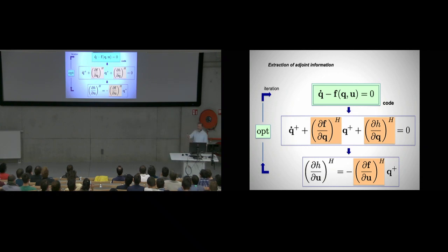Okay. And one possibility, there are many possibilities, but one possibility is you sit down and you derive it. You take your equations and you go through exactly that integration by parts to figure out what this equation, this F_Q, looks like in my case. Now, if you have the incompressible Navier-Stokes equations for a simple geometry, that one has been done for you. There are plenty of papers out, and you can even do it yourself in an afternoon. But if your F happens to be the compressible Navier-Stokes equations with reactive flows and non-equilibrium and multiphase and level sets, good luck with that one.